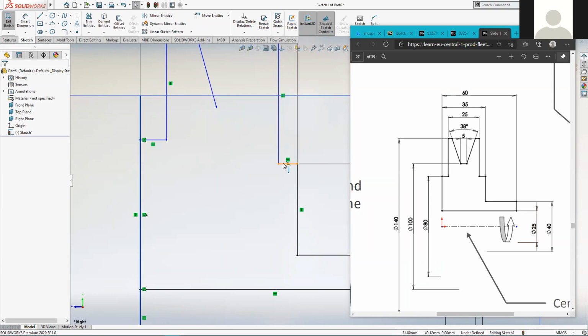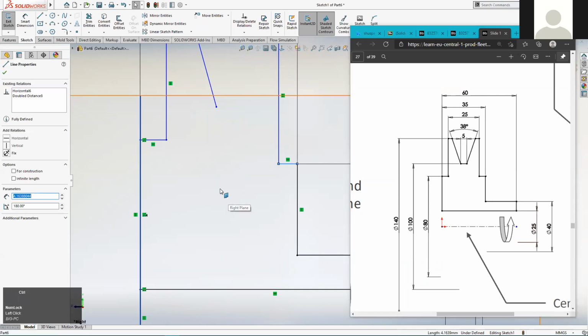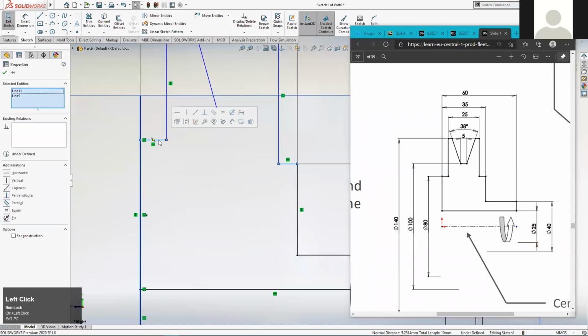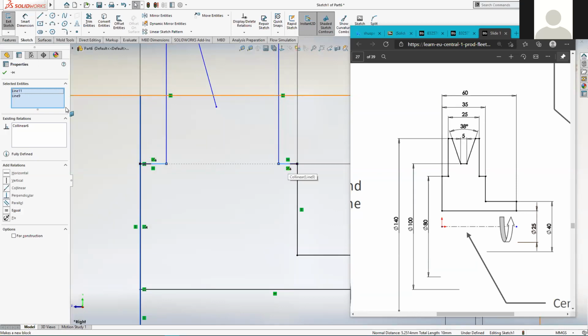So there, let's say. Get that edge selected, hold down Control, do the same with this edge, so the entirety of the edge. And then of these options, it's not really horizontal because in this sense, that would apply to the edge itself. And these edges have already been locked to horizontal. You can see individually, each edge is being held at horizontal. So that's not what we want. It's that option there. Make collinear, which basically means they occupy the same sort of level, if you like, collinear in this instance. So there you go. They've been locked to be collinear with each other.